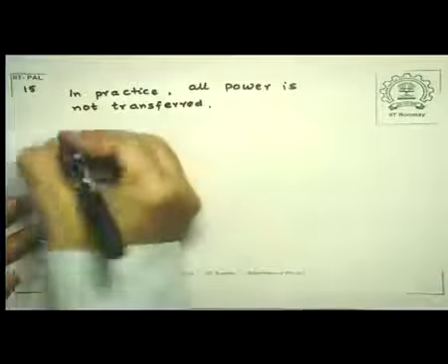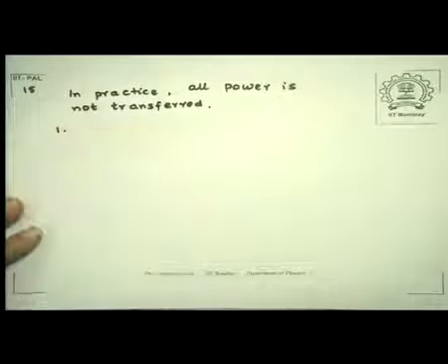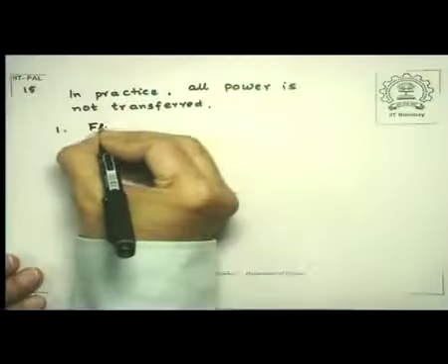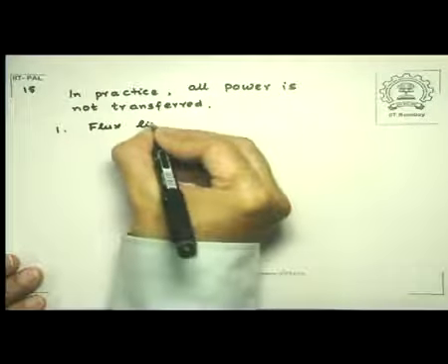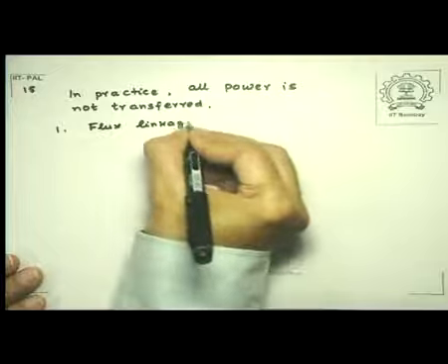Now what is the reason for that? So number one is that all the flux will not link to both the primary and secondary. This was one of our assumptions. So the flux linkage is not total.